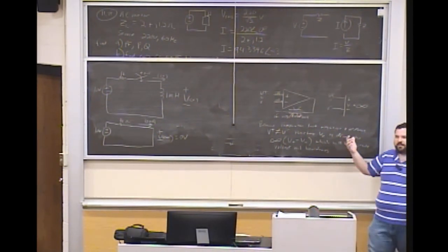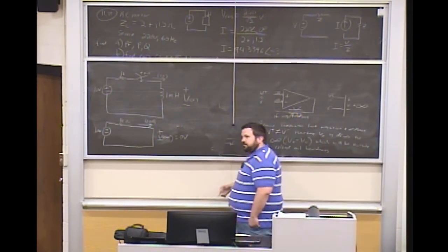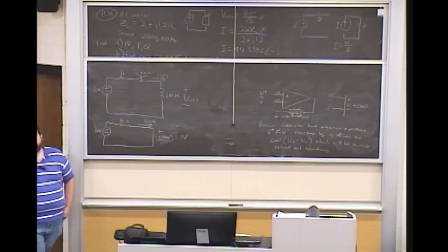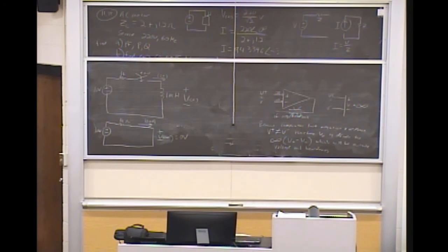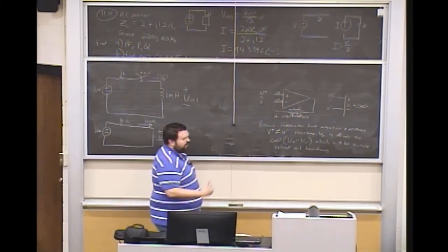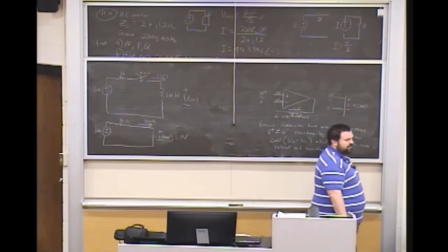And we exploited that to our gain on the project, right? We wanted to know, is this bigger than this? And what we effectively made those two op-amp comparators do is saturate either the positive rail or the negative rail to indicate this voltage is bigger than that voltage. One of those was your known voltage from your simulation, whatever voltage you got out at 20 degrees Celsius.